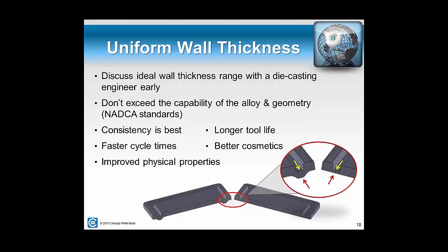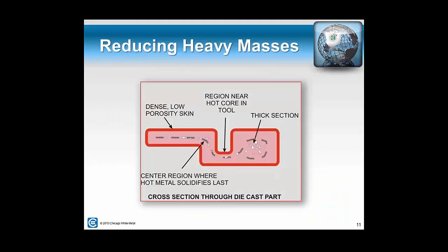The one on the left is what we would consider a good case. The thickness is fairly uniform throughout the cross-section here. On the right, the thickness goes from a relatively thick section down to a pretty thin section and then back to a thick section. And that is a potential issue point with the tooling and how the part is going to fill. So that's some of the things we'll look at and discuss with you when we see areas like that. If we can address them ahead of time, prior to the tool design and tool build, that's the right spot to do it.